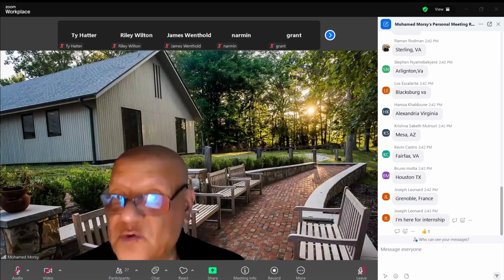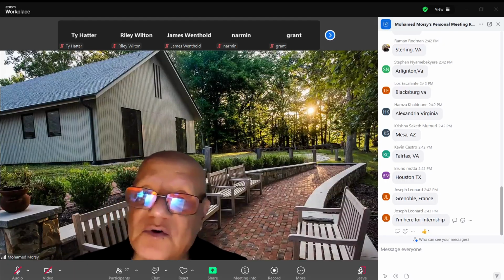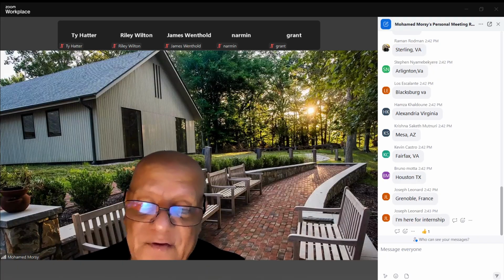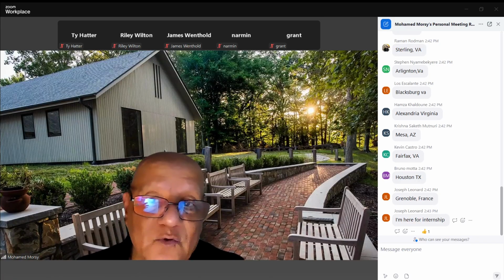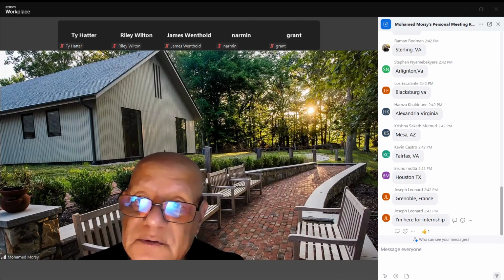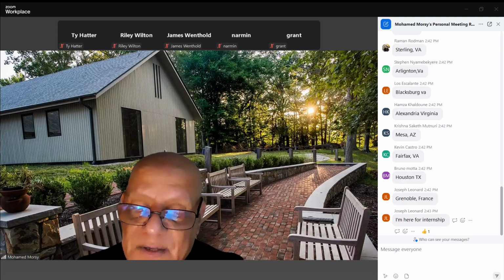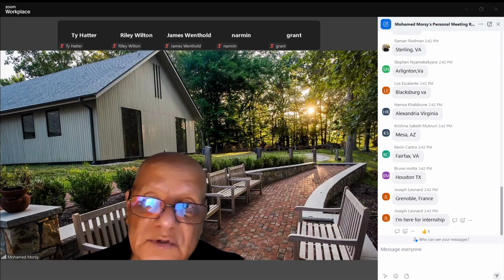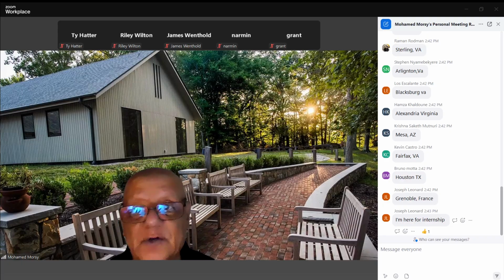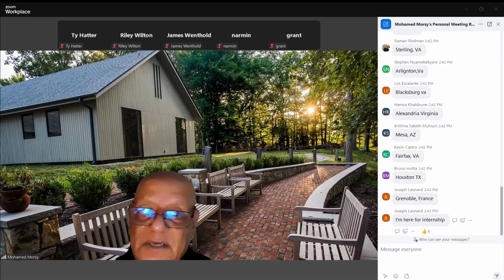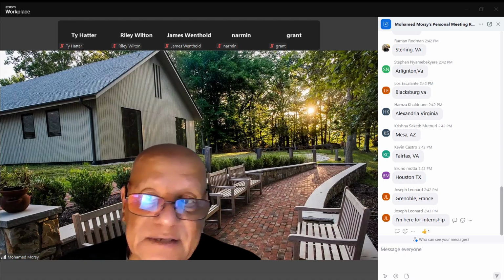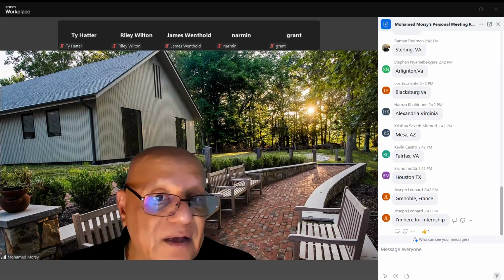Yeah, if we have double errors in the message, like the examples we did, if we have odd parity and we have double errors, like we have 1101010, for example. If we have double errors like 10000, so there are 2 errors. 2 ones change to zeros. So we still have odd parity, but the message is wrong. So if we have double errors, we can't detect the error. So this is another disadvantage.